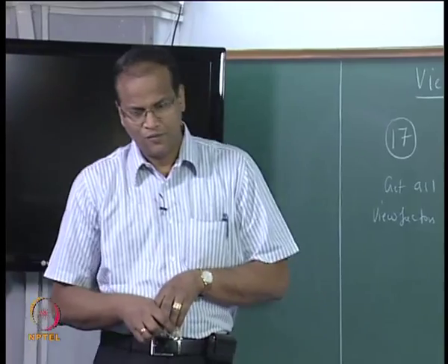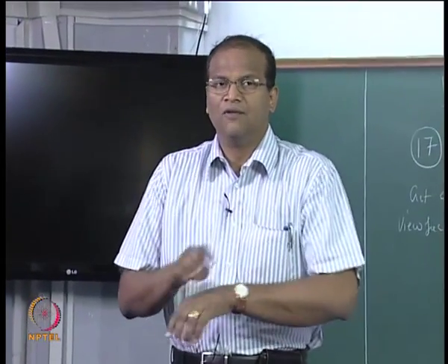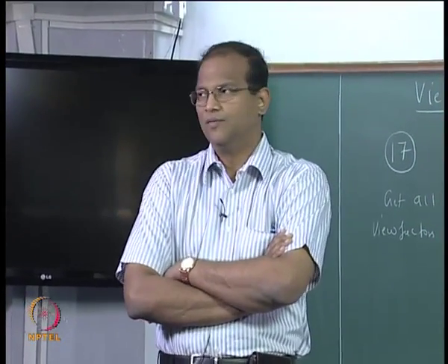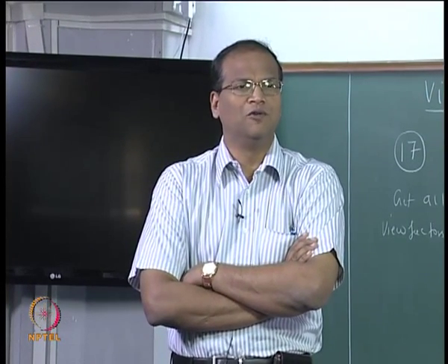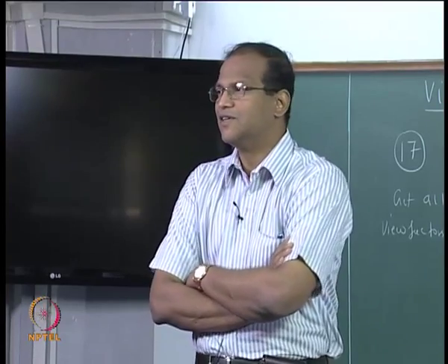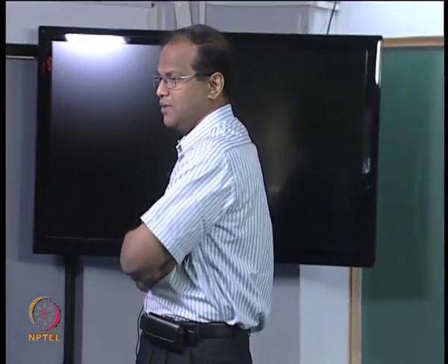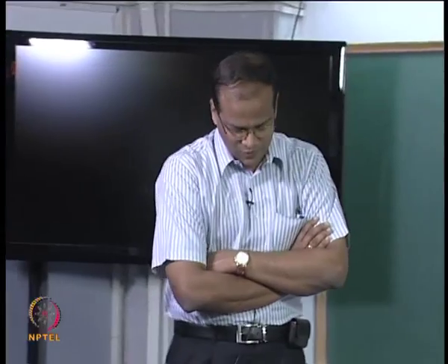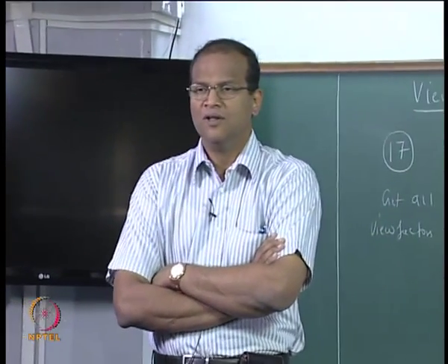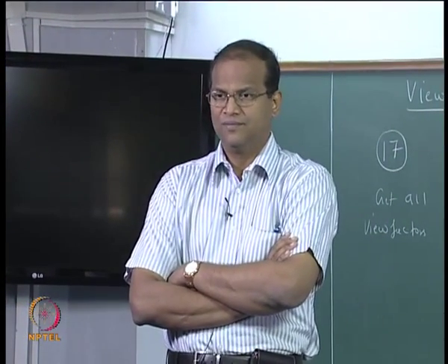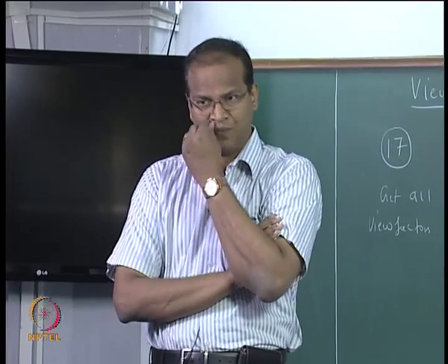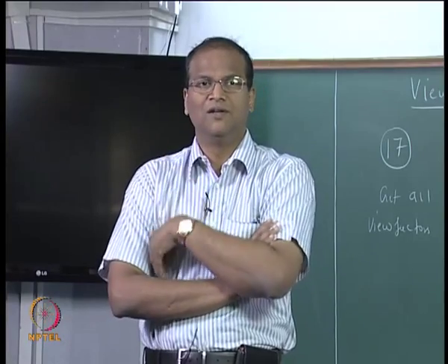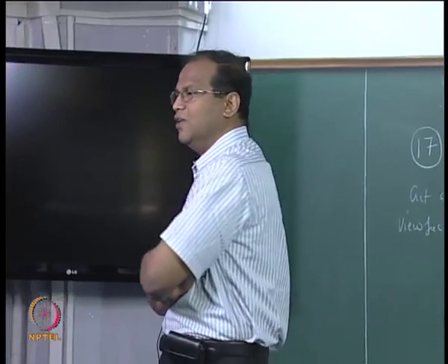So, in today's class we will solve a few problems which exploit the view factor algebra, and to the extent possible we will try to obtain all the view factors in an n-surface enclosure system by using view factor algebra itself. Towards the end of the class maybe we will work out one problem in which we have to use the double integral, okay. It is not actually a double integral, but a double integral over Ai Aj, in order that you are able to appreciate how we can use this fundamental formula to derive view factors.